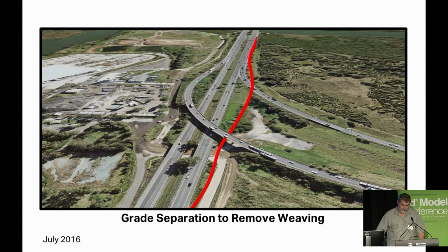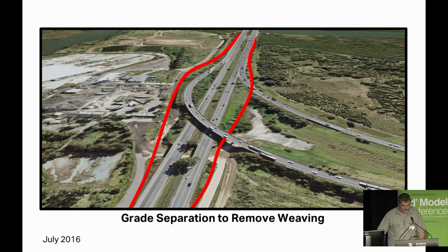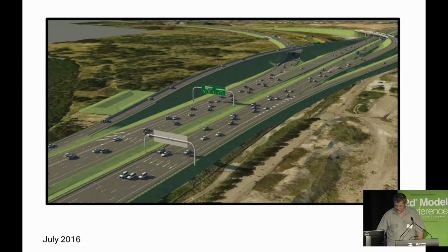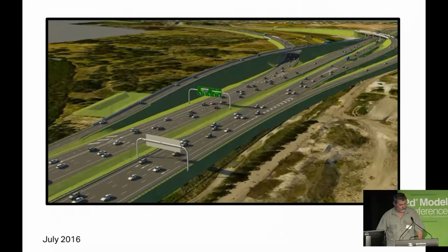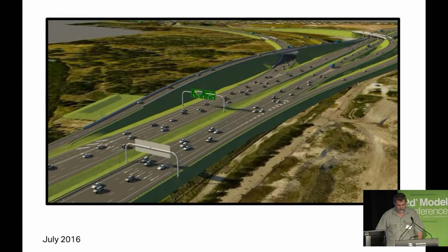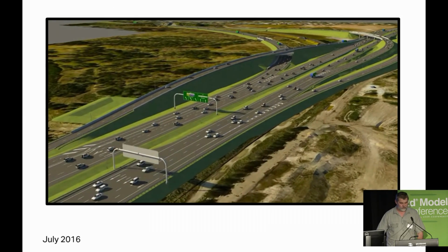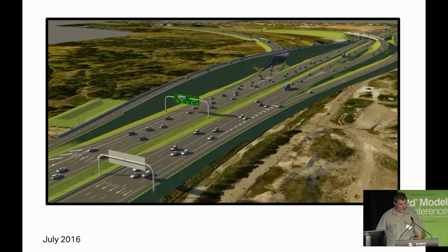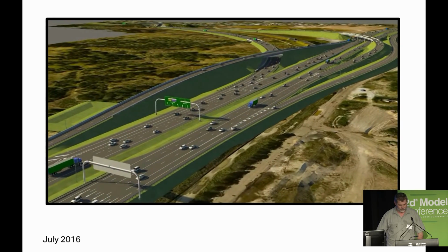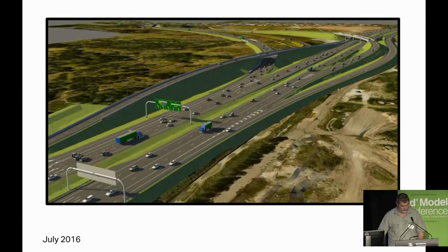In this example of a typical solution, the southbound on-ramp traffic connected to the major arterial road via a grade-separated connection road that utilised the free span under the existing motorway overpass. And the northbound traffic is moved to the outside lane prior to the northbound motorway merge. Our design layout is then passed to the traffic nerds to model, and in this example, the resulting traffic flows are combined with a visualisation model that shows actual modelled traffic volumes and not the random traffic patterns that are typically shown in these kinds of visualisations.